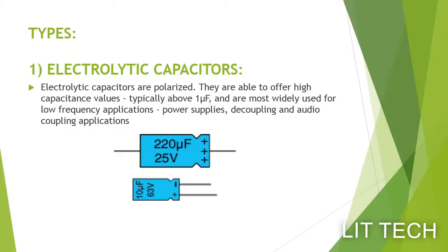Electrolytic capacitors. Generally, electrolytic capacitors are polarized. They are able to offer high capacitance values, typically above 1 microfarad, and are most widely used for low-frequency applications, power supplies, decoupling and audio coupling applications.